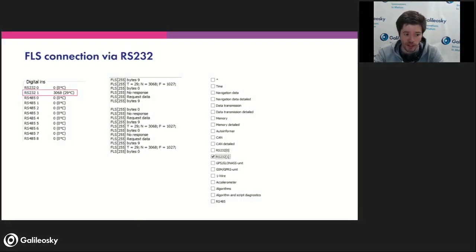This is how the data is shown. So here you can see that the digital field level sensor not only gives us the value of the sensor, it also shows the temperature of the fuel, which is quite crucial when you have to calculate the fuel consumption or work with the fuel level depending on the season, like the temperature outside and the state of the fuel, because you know gasoline or diesel is different in winter and in summer.